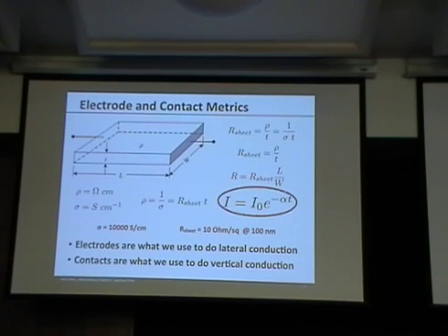So this tells you something about how the conductivity, i.e. resistivity, of this layer is going to be important in your actual device, and it tells you something about how large you can make that device, the area of that device, before you have too much electrical loss due to too much resistance in this layer.